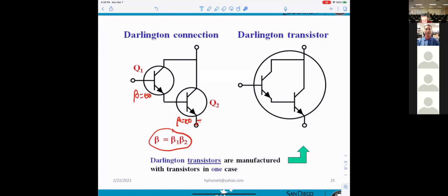For some reason, DMM low touches to here, it will be cooked right away, the circuitry. The thing is, it's high current. Or mostly people using an oscilloscope, and the ground of the oscilloscope is easy to touch into here. So that's why the circuitry will burn right away.